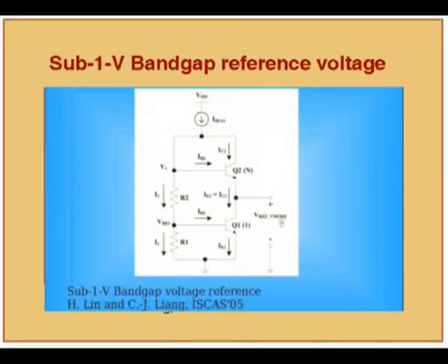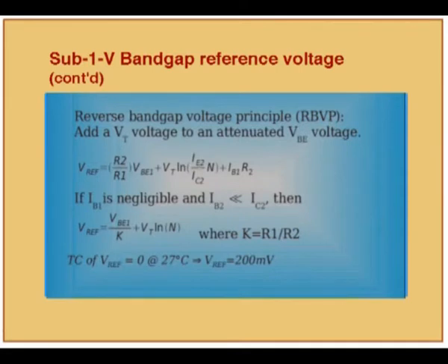So if you look at reference, it is this VBE plus this voltage, V1. And to get value of V1 will be this drop, which is a function of this, plus this VBE itself. So if you write just KVLs and replace the relation for I versus VBE, you will get this.